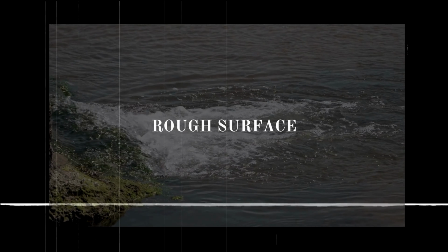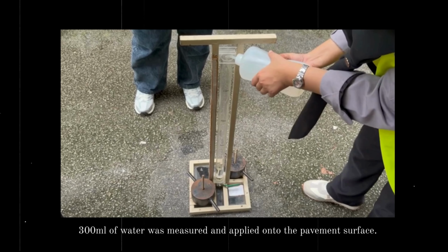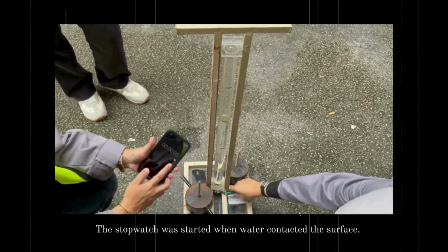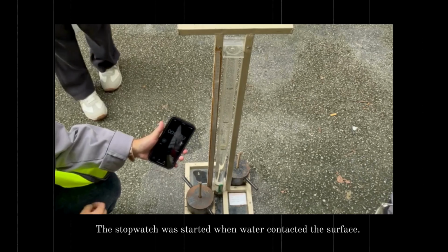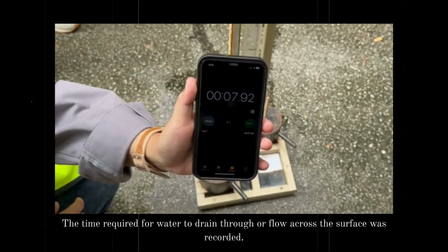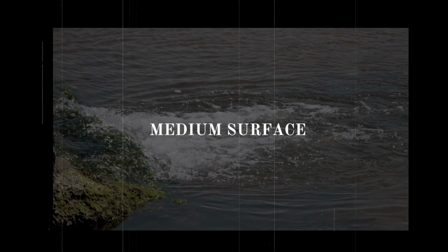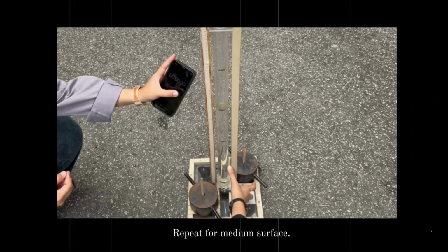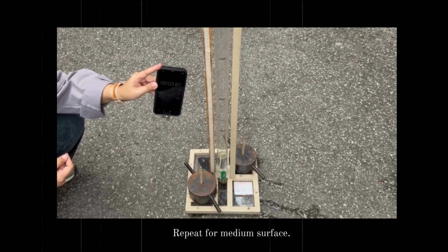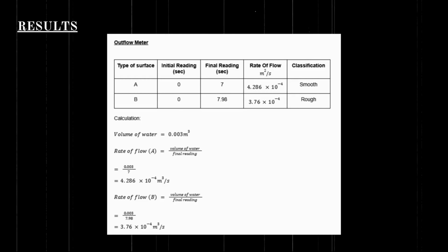Rough surface. 300 ml of water was measured and applied onto the pavement surface. The stopwatch was started when water contacted the surface. The time required for water to drain through or flow across the surface was recorded. Medium surface. Repeat for the medium surface. This is the result obtained from the test.